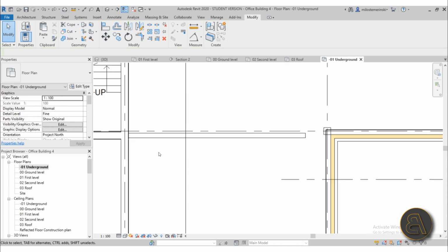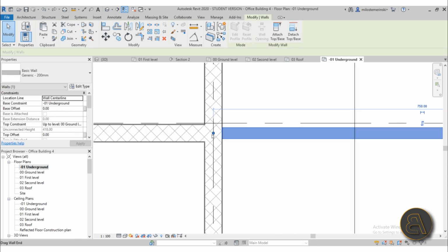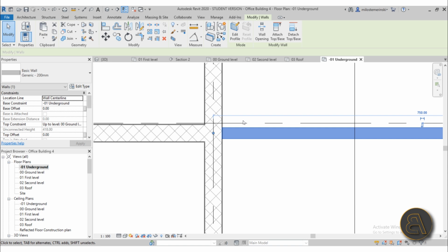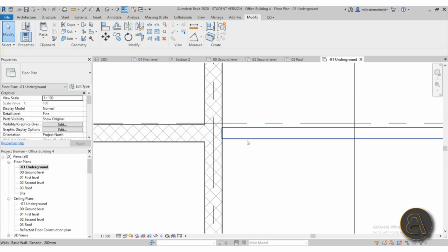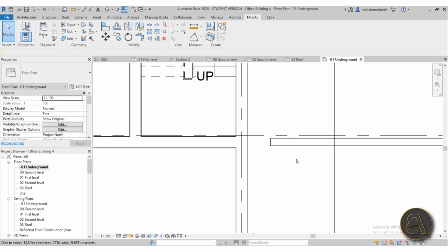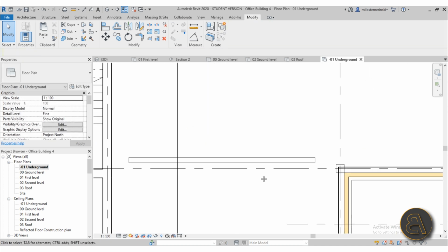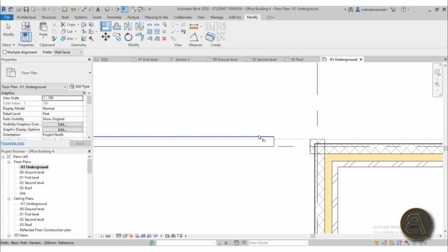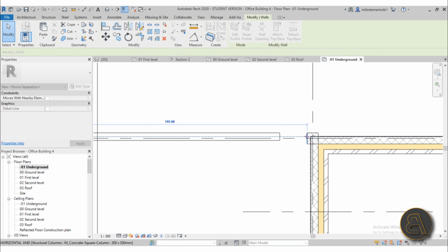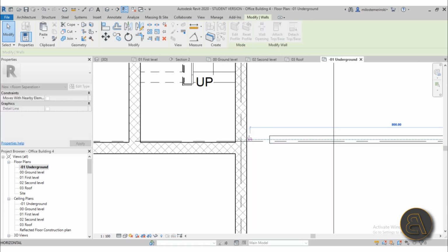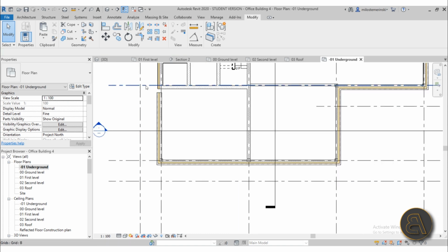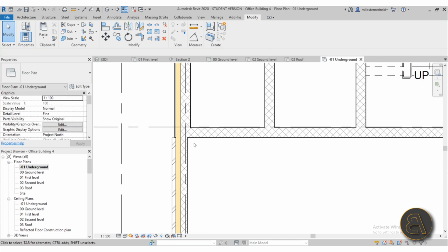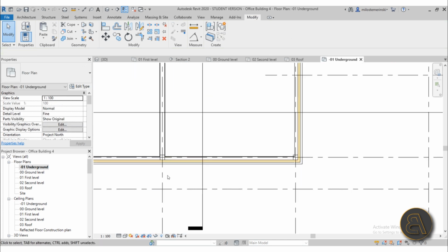That's one of the problems that you'll have in Revit constantly. When this wall is attached here, as you can see, it's attached to the same point where this wall is attached. So if we start moving this wall around, it will drag this wall with it. A good idea is to unconnect that and then move it freely. So we can maybe move it here, or align it to this edge over here, and then extend it, and we'll play around with the layers of this wall and maybe some doors later on. Here it might be a good idea to connect these. There we go. Okay, these are connected, and this looks quite nice.